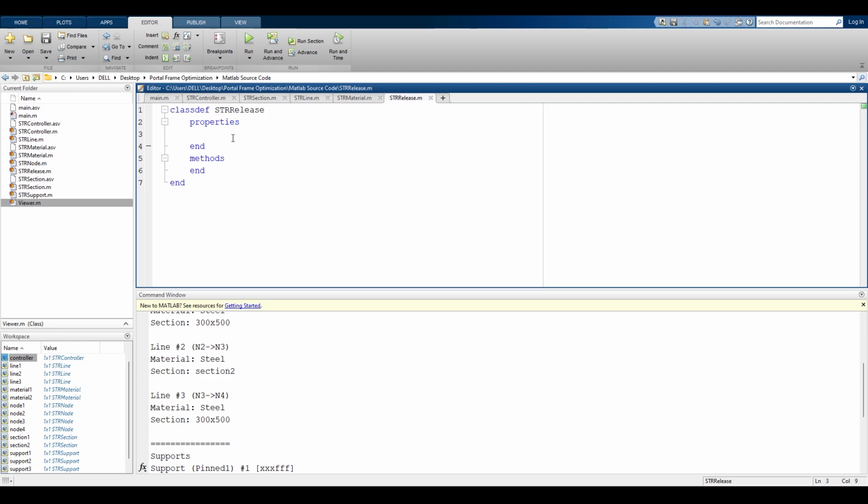However, I know that you might say that this includes extra complications to the finite element method, and you are right, because when I add a node, this would increase the number of equations by 6, which increases the calculation effort. And that's totally true. However, this way of defining releases is more consistent and is easier to handle without a lot of sweat.